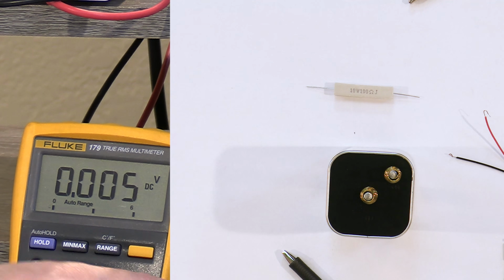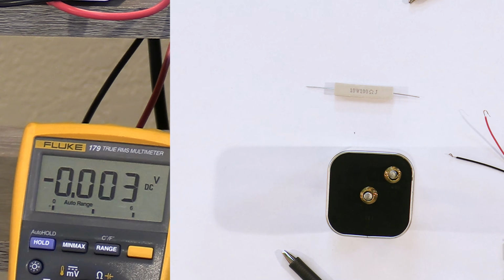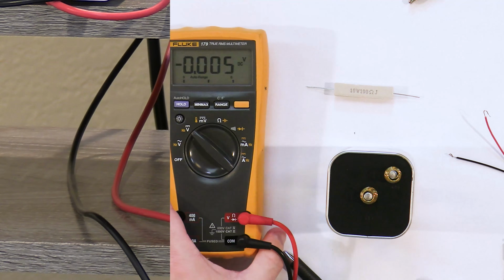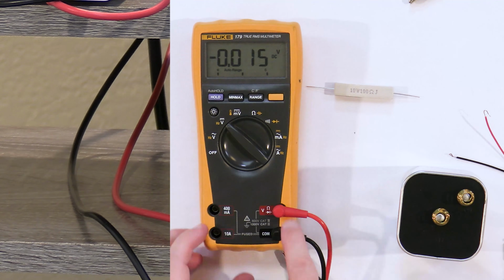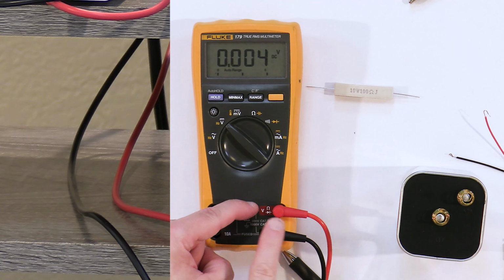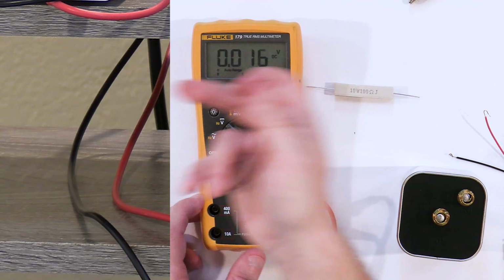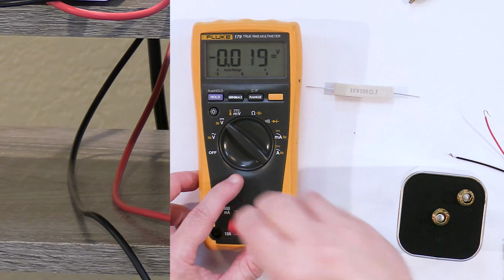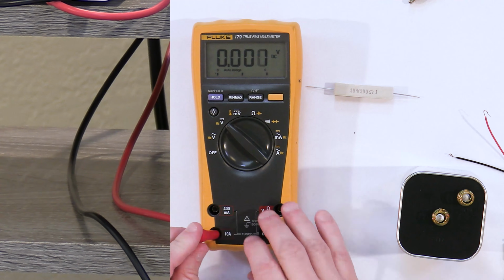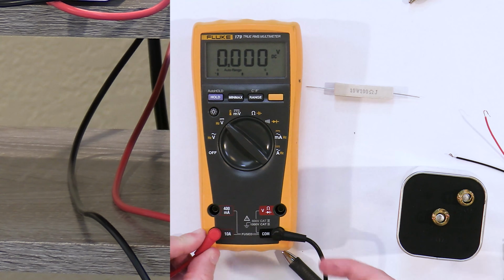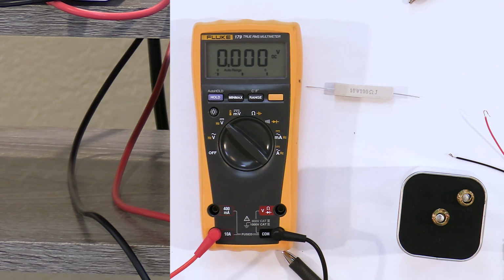Now, we have to learn how to measure current. The way I have this meter set up right now is as a voltmeter. Your meter, whatever meter you have, might be a little different, but you can see that to measure voltage with a V right here, you have to have it over here. To measure electric current, the electrons have to flow through the device. So you can't connect it here. You need to connect it over on the other terminal. If you're measuring current, you have to push the current through the device, so it has to be connected over here.